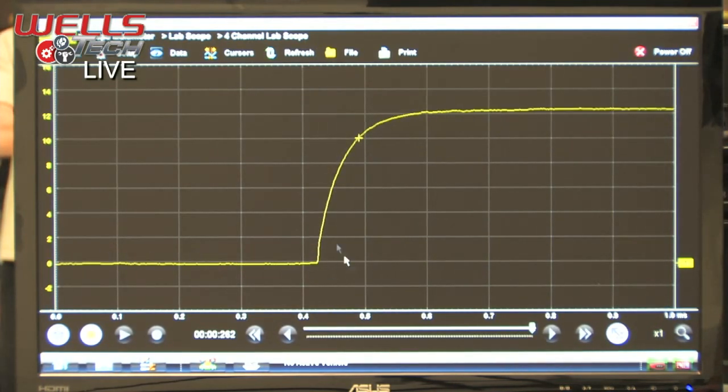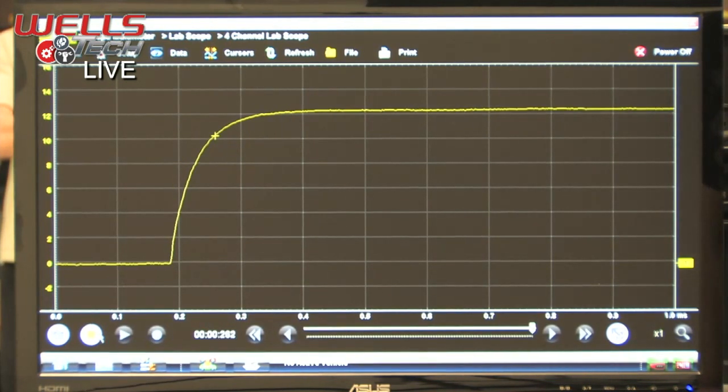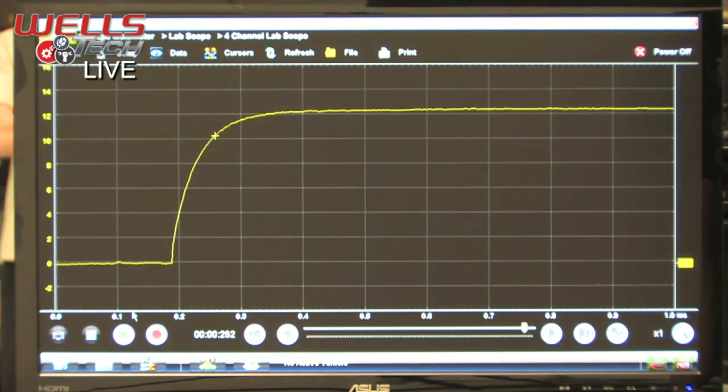And you can see immediately it looks a lot different. The trigger is picking up the signal and putting it right on the screen. If we move this thing up or down, it adjusts where it sits. We can bring it back here. So that looks very nice. All right, I'm going to stop it here. You can shut it off. So by setting this trigger, you can see really easily now what's going on with the cam sensor, but we don't know the full story because we're zoomed in way too tight.